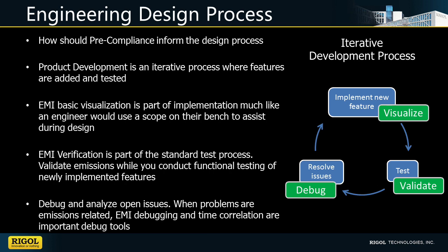Here, let's think about a basic iterative development process where engineers implement new features, test, and then resolve issues. With EMI pre-compliance measurements, we can use basic visualization, just like you'd use a scope on your bench when you're building and designing out these new features.